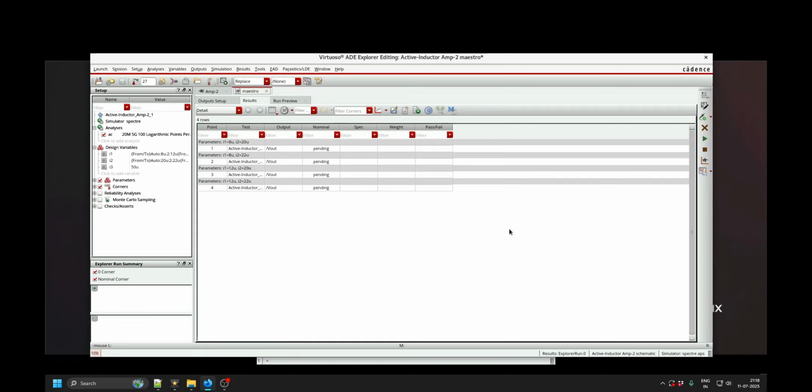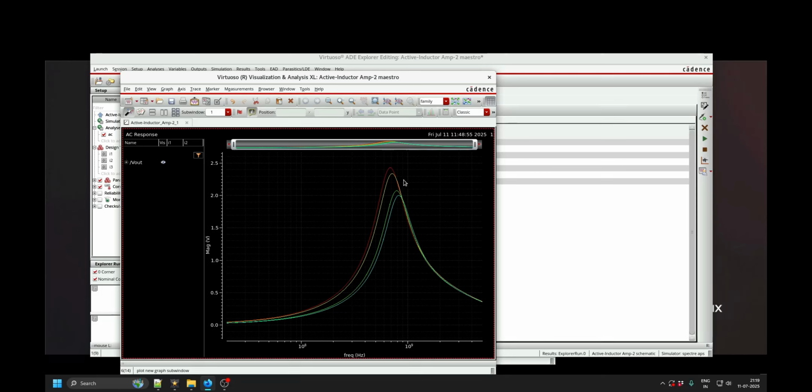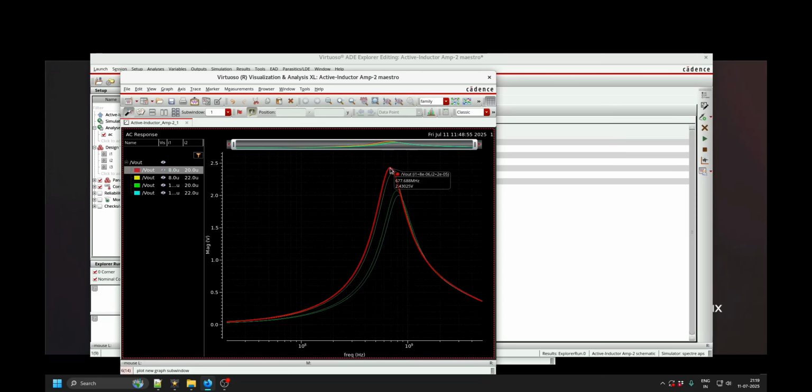So this is how you can do it. You can decide the values of I1 and I2 for your design. The only thing is that this circuit is very sensitive to the tuning currents, so it is better to take I1 and I2 from a band gap reference voltage.